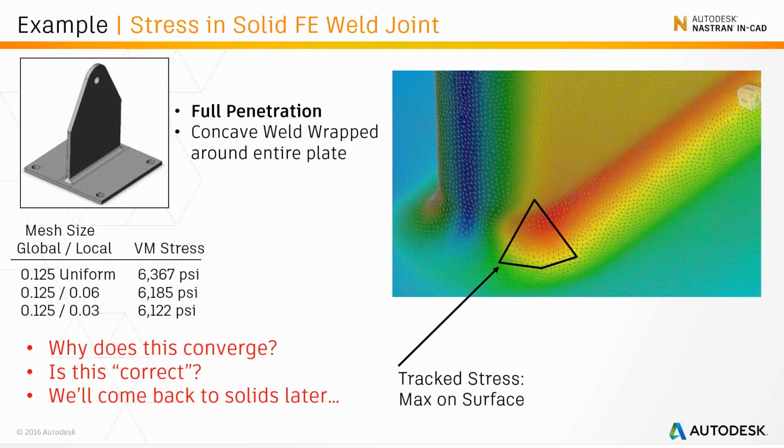What happens if we assume that everything is bonded and we have a nice smooth weld around the side and it maps to a post-welding grinding operation? Sure, it will converge, but does this match reality? In most cases, people are trying to make their finite element model give them answers that don't match anything that's happening in reality.